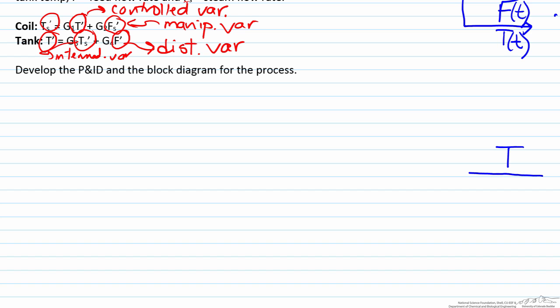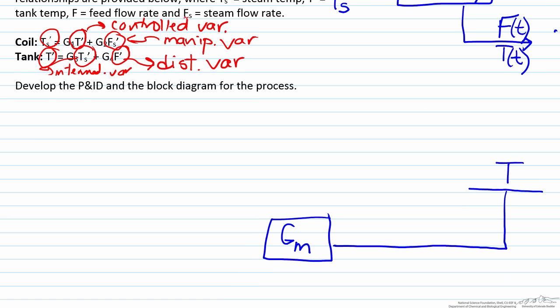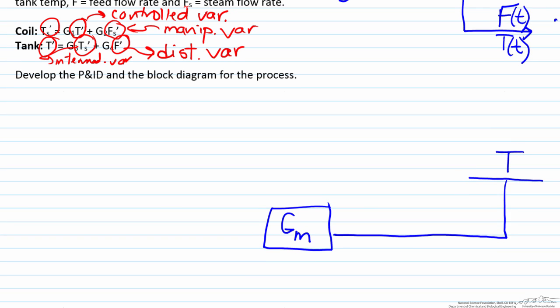So in order for this control system to work, the temperature has to be sensed and transmitted by the temperature sensor shown here in the diagram. So therefore, this will represent the sensor transmitter block. What will come into this is a temperature in degrees Celsius or some other units, and what will come out is some representation of this in transmitter output, or in milliamps, so that the controller can understand it.